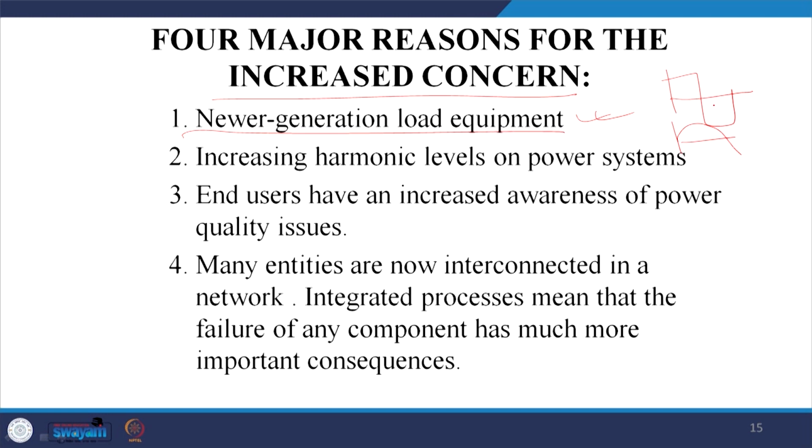So, the rate of change of voltage is quite low, and since in this kind of nature it will break down the insulation of the winding, thus it degrades and deteriorates its performance, its lifespan also decreases, and ultimately you put in the cost. Instead of 15 years it will last 6 years, and its performance also will be less.